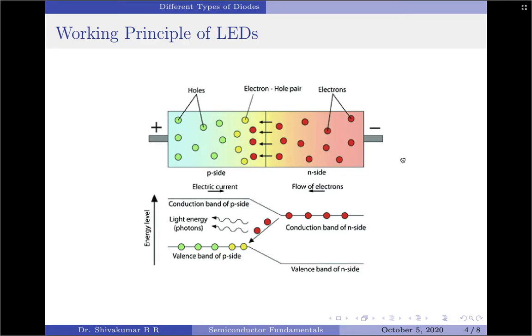By adding an impurity, which is known as doping, extra atoms are introduced, effectively disturbing the balance of the material. These impurities, in the form of additional atoms, are able either to provide free electrons, which is n type, into the system, or suck out some of the already existing electrons from the atoms, for example p type, creating holes in the atomic orbits. In both ways, the material is rendered more conductive.